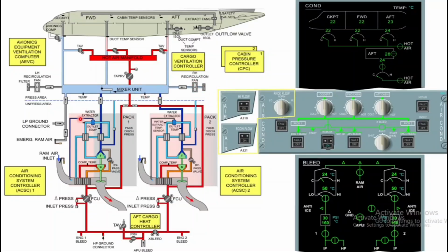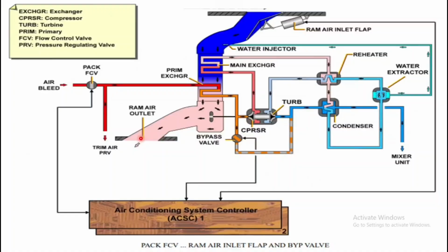This will reduce the bleed demand of the pack, because you are utilizing the same air. So this is also very good information to know about the recirculation fan. And this mixer unit, as I already told, is connected with the emergency ram air inlet. And then next we'll go